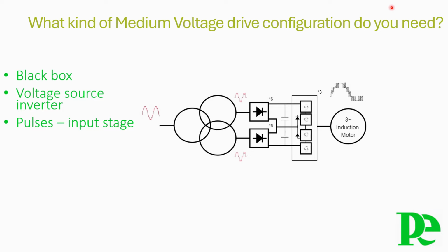The 12-pulse drive will generally not meet the requirements of voltage and current harmonic distortion imposed by current standards. Going for a higher number of pulses, such as 18, 24 or even 36, will further reduce the harmonic distortions, but this comes at a price for the rectifiers, the transformers, and at a higher footprint.